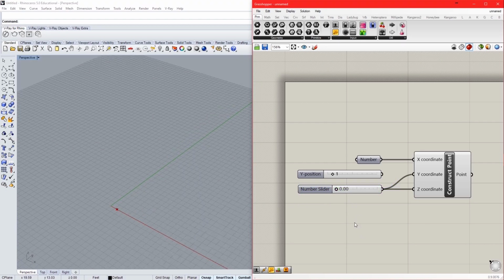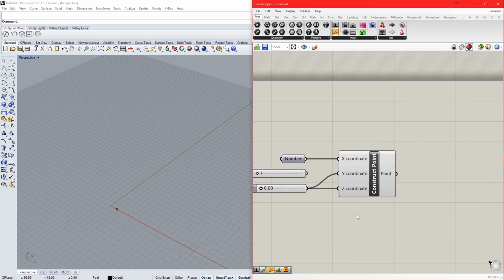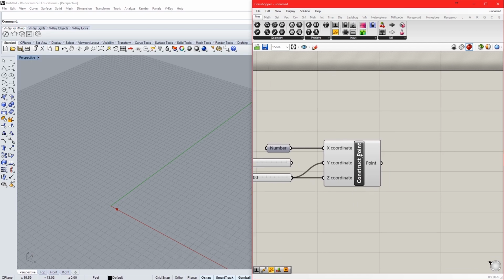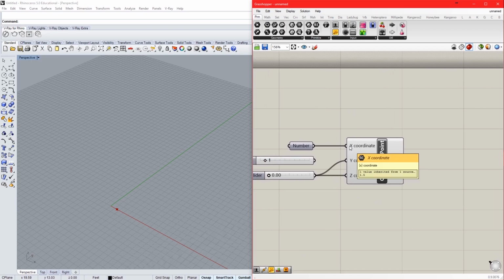And now I'm going to create a tower, right? So first thing for creating a tower is if I want to say, let's say I want every floor plan to be the same shape, but I want it to rotate, right? I want it to be like a spiraling tower. So from this construct point, I'm going to define a very simple shape. So I'm going to say that I want to outline this floor plan with a curve. So remember we stopped at the vector tab, now we'll go to the curve tab.